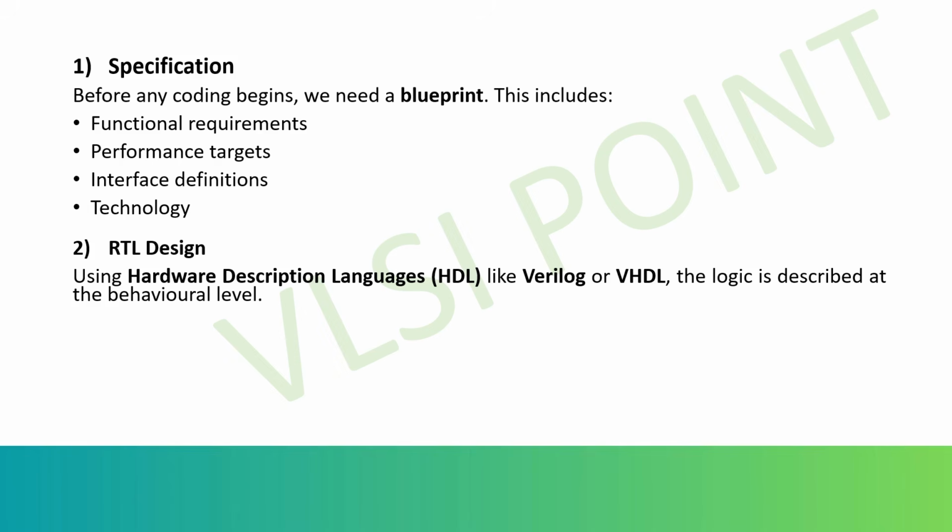Make sure to always write synthesizable code, and you can avoid any kind of delays, then use non-blocking assignments and follow coding guidelines for naming, indentation, and reset handling in order to make it synthesizable. And remember, guys, RTL design defines what the circuit does, not how it will be built physically.